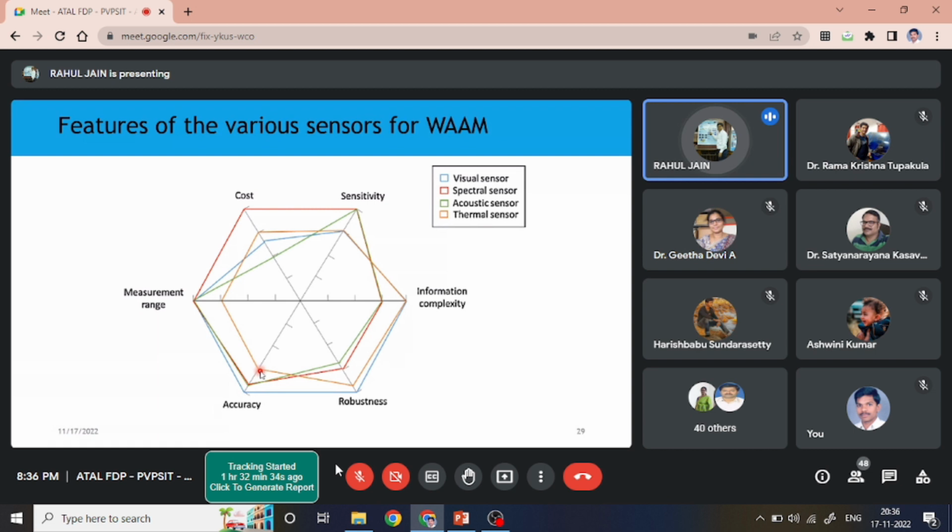So in order to make this thermal sensor more accurate, you need to do multiple things. One, because most of the thermal sensors are IR based, emissivity matters, because we know it works on the principle of radiation, which is emissivity multiplied by the Stefan-Boltzmann constant multiplied by T to the power 4. Now this emissivity is a very variable thing. Why? Because emissivity is a function of surface property, and is a function of temperature. A lot of people make the mistake that they just Google it, and whatever emissivity is there for a particular material, they put it. For example, if emissivity of aluminium is 0.7, people will just blindly put the 0.7 value.